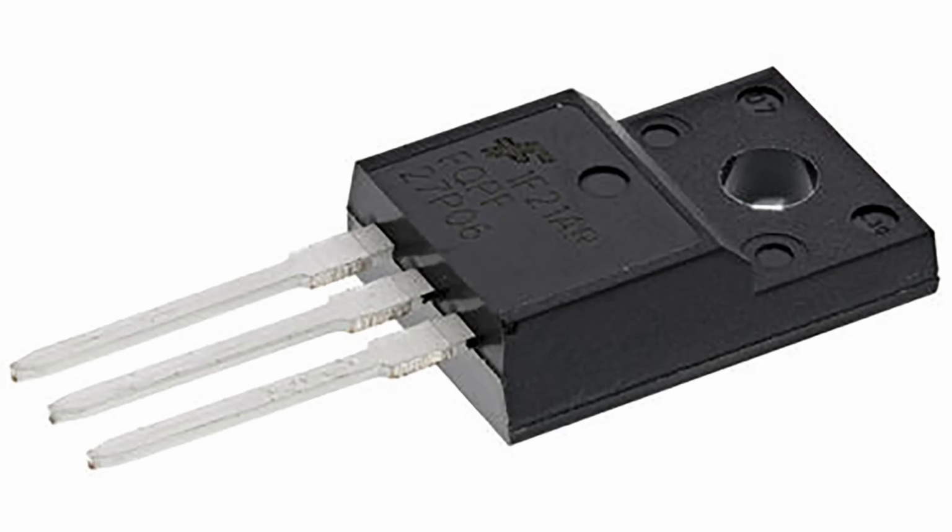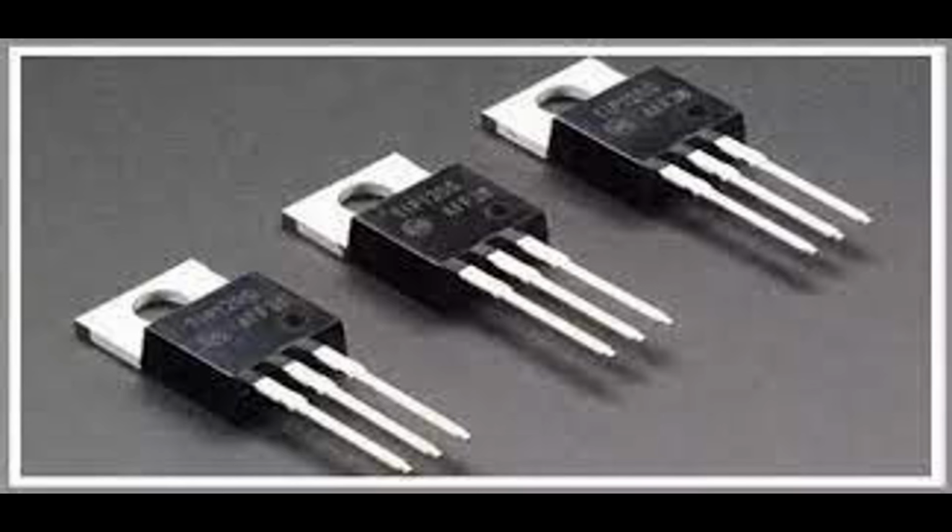5. Switching behavior. Turn-on transition: when V_GS exceeds V_TH, the channel starts to form, allowing current to increase rapidly. Turn-off transition: when V_GS falls below V_TH, the channel closes, and current stops flowing.